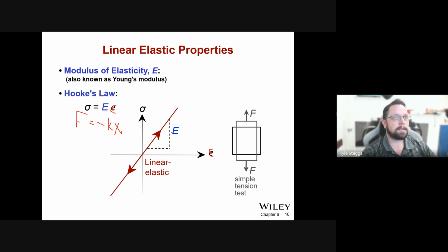This is our fundamental stress strain graph. So instead of x and y, we have stress and strain. So this is movement relative to the original length. This is the stress applied. So the force divided by the area. That tension force, what that's doing is stressing that material out, and that tension is reducing the effective diameter, or the cross-sectional area.